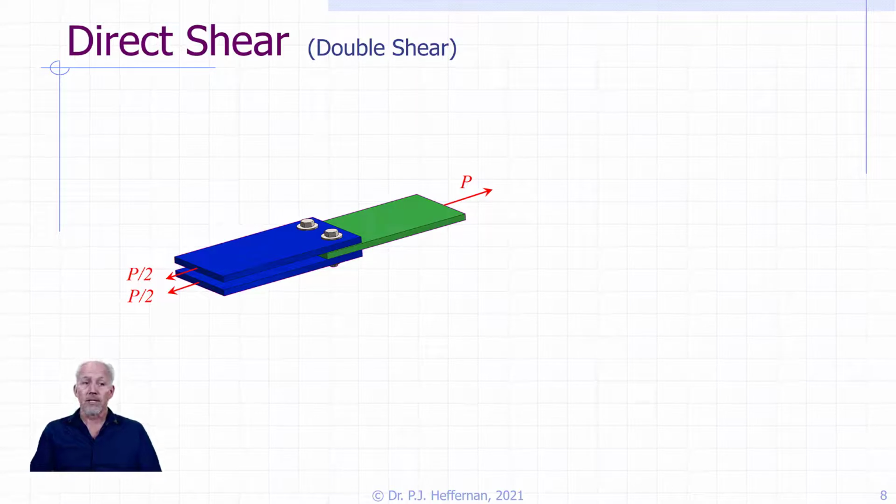So a physical representation of what we just looked at, only in this case we have a different configuration where we have two plates bolted to a single plate. This also is a fairly common configuration in the construction world, preferable to the kind of lap joint type construction we saw before, because in this case the uniaxial forces are always symmetric about the longitudinal axis, whereas that wasn't always the case before, which has some issues which we can talk about.